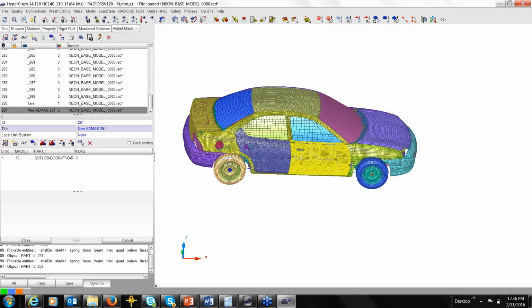The key there is to use as big an element size as you can. So in the explicit, you want to stay within 2-3 mil. We recommend about 5 mil, but you can't meet that 5 mil most of the time. But you want to stay within 2-3 mil. You don't want an element size of 1 mil or 0.1 mil.